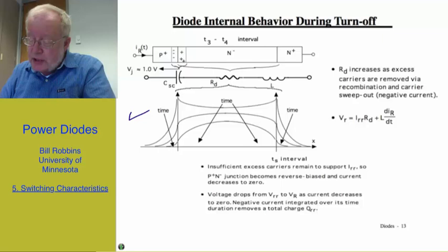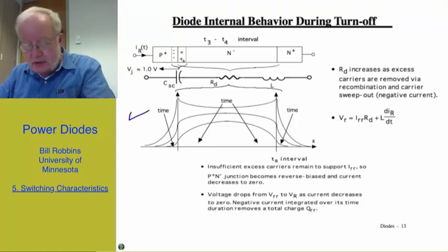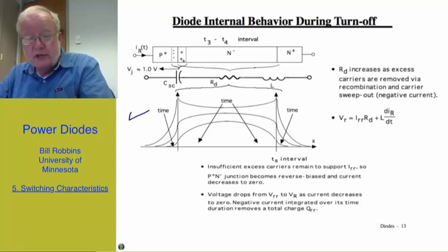So that means we're changing the charge on the capacitor, and because of the inductance we have an L times di/dt. During that time interval T5, where we can have some very steep changes in current in relatively short periods of time, that L times di/dt can give us overvoltages which may approach or even exceed the breakdown voltage of the diode.